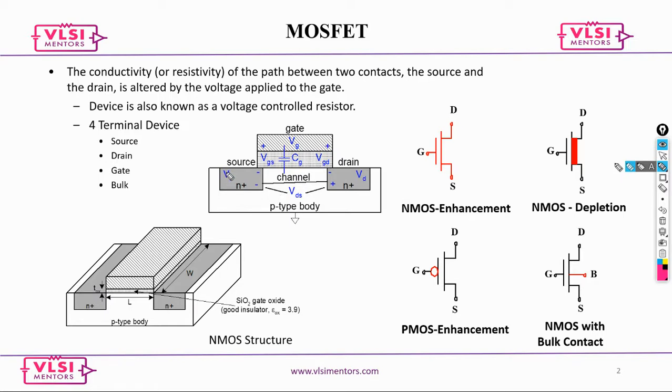Look at this. So this is your silicon substrate. Now what is it you are doing here? First thing, you are adding impurities, converting it into N type. Now this is also converted into an N type area.